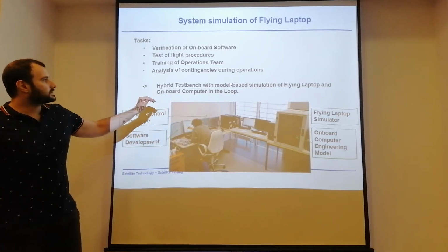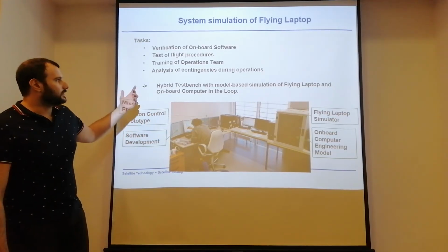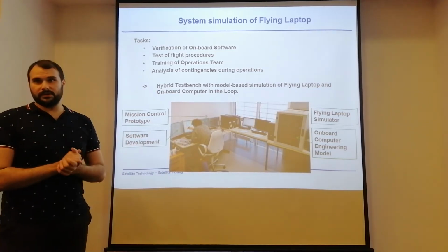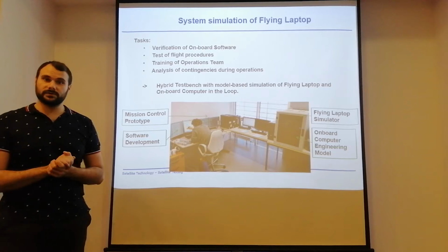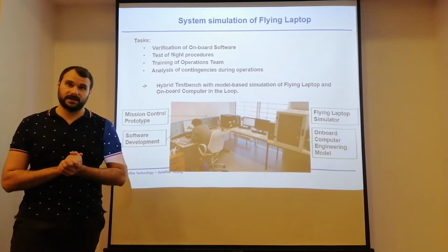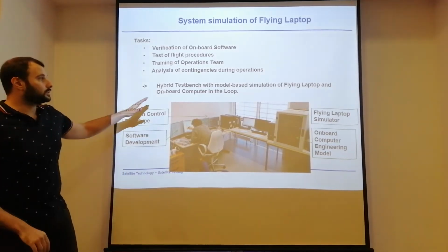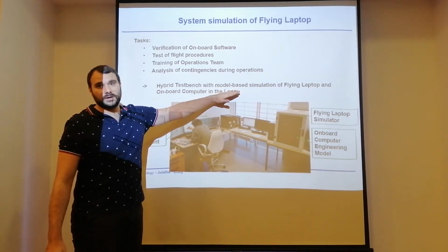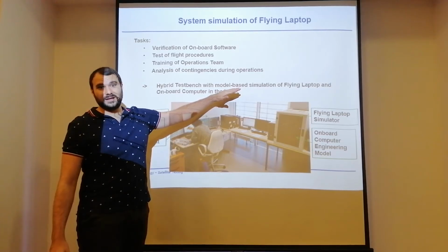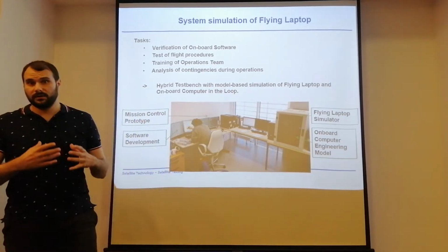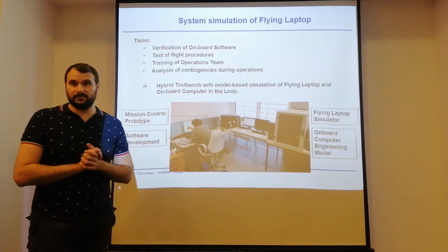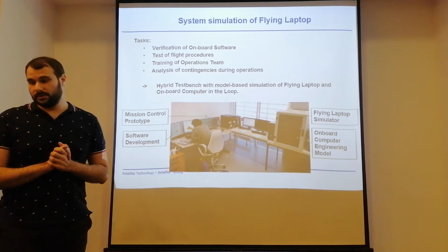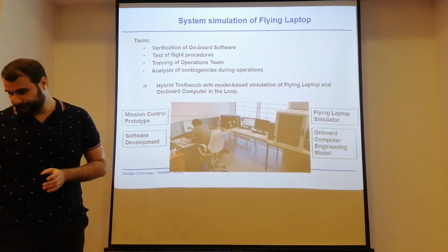And this hybrid test bench with the model-based simulation of Flying Laptop is very unique at this point and enabled a lot of possibilities for testing, especially for the environmental tests. However, you are prone to the accuracy of your models. So you really need to make sure that all your models are really close to reality to have a realistic outcome and realistic results of your system simulation with this hardware-in-the-loop hybrid test bench.